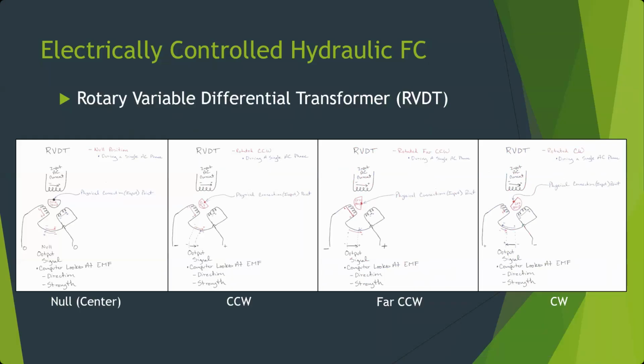You use it with, in that case, the rudder, but by routing air from the propeller across the rudder to swing the tail around. In the case of these, the main thing we used was differential braking, but you could also use differential thrust to some extent. Wing-mounted engines definitely have much more differential thrust. It just takes some time to react. So if they do go bad, there are ways to deal with it.